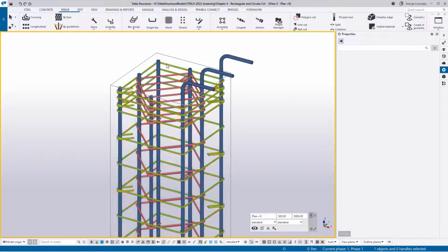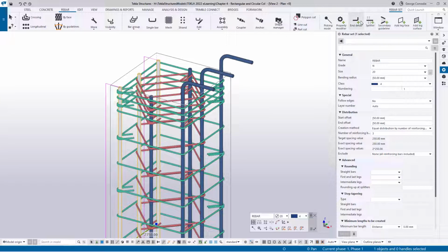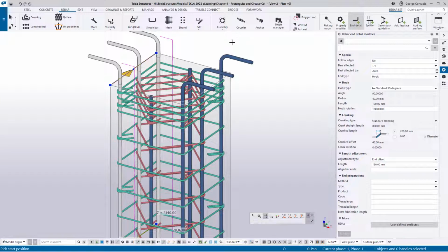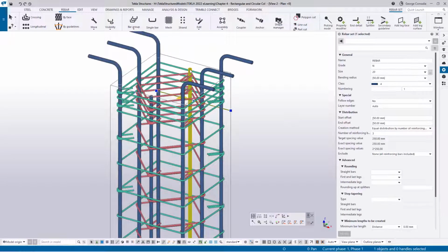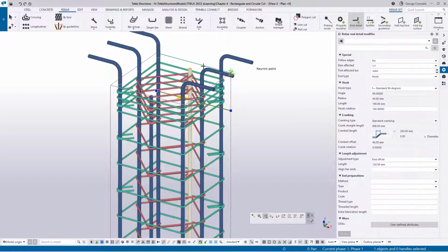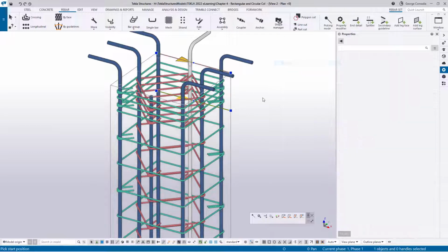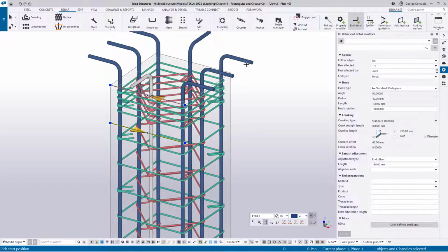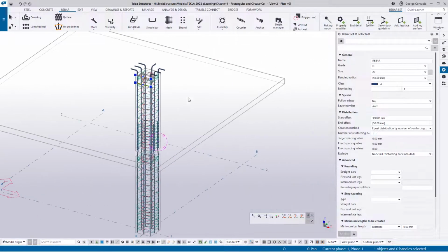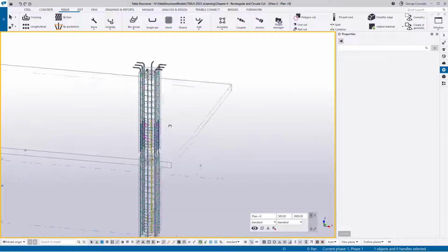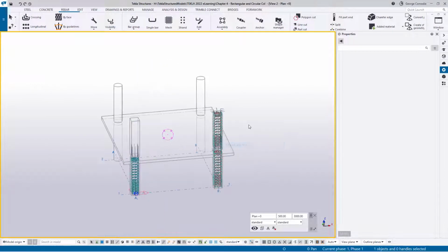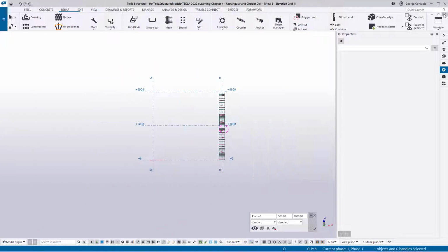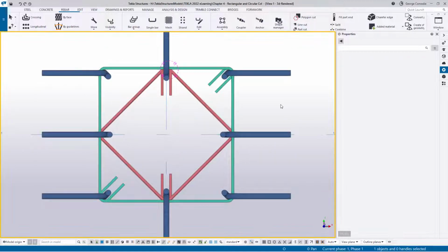And then what I can do is I can click on the opposite side, end modifier. Tekla remembers the settings. I can just hover over that edge. It fixes that up. I can click on this one, end modifier, hover over this edge. It fixes that. And then lastly, pick this end modifier, this edge, and just like that, we have now completed that column. So if I go workflow entire model, and let's just go to our rendered view, not this view and not that view, but this one.